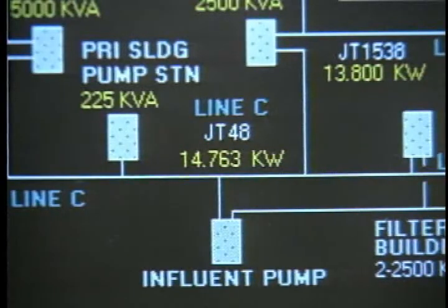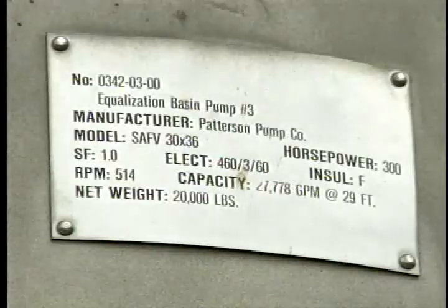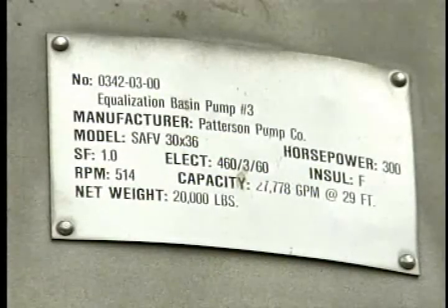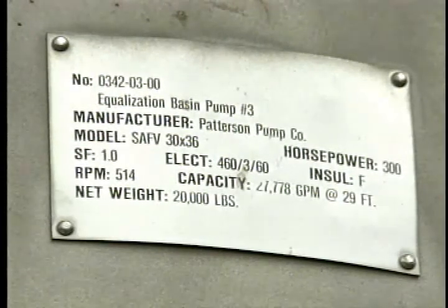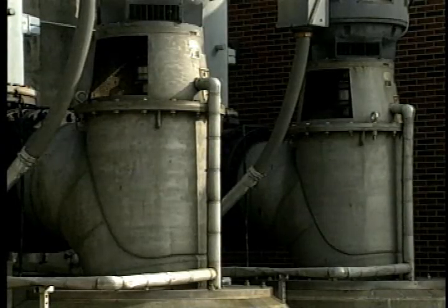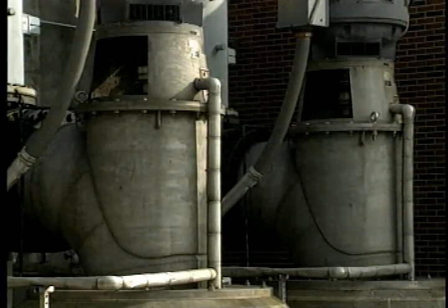With most impeller designs, if the system pressure is reduced, both the flow and the current draw of the motor will increase. The motor may become overloaded and burn out quickly. Sometimes, increased power demand will signal a change in the specific gravity of the fluid being pumped. If the pump must move a heavier fluid, it will have to work harder, but there may be little if any change in the pressure or the flow.